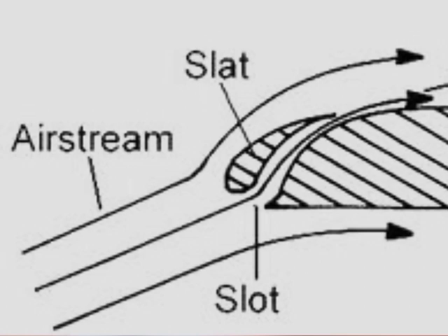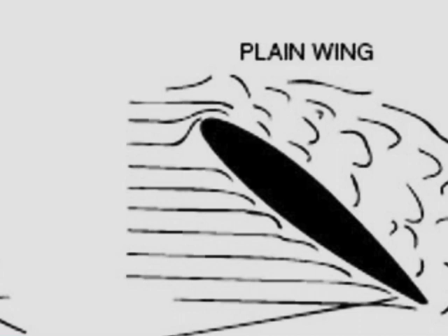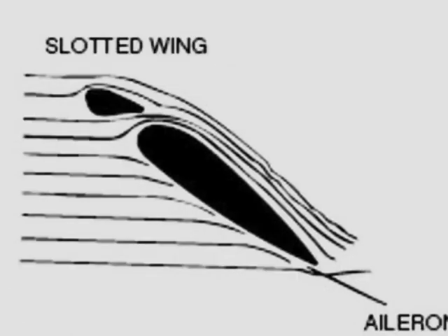How should we prevent this? The manufacturer has found a very good and excellent way to prevent this. When we extend the leading edge slats, slots will be made between the leading edge slat and the leading edge of the wing.